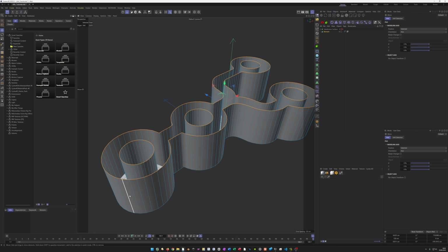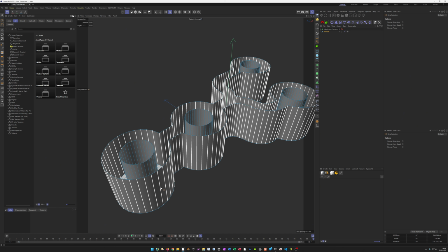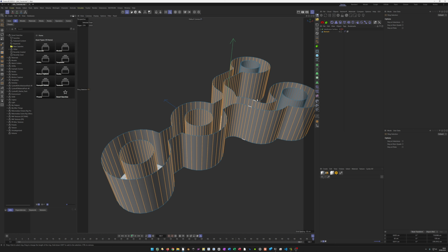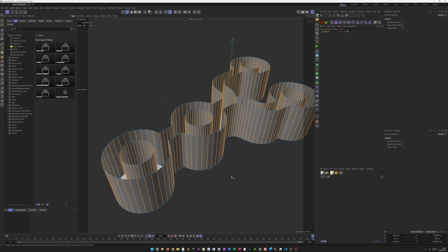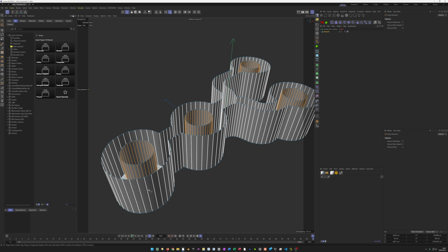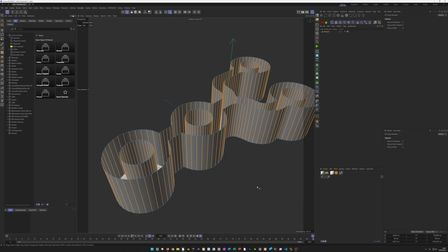And I want to make some subdivisions here on the height as well. So I want to select all these edges with UB. This is a ring selection. Okay, whoops. And we can select this, this, this, and this. It can go faster when you go to the side view here and make a rectangle selection and say visible only disabled. Then you have the inside and the outside, so I don't have to change the viewport every time. Good, I have this, and now with MM, so hit the M key twice, we get a cut. We cut the edges. So MM, another one, MM, one more.